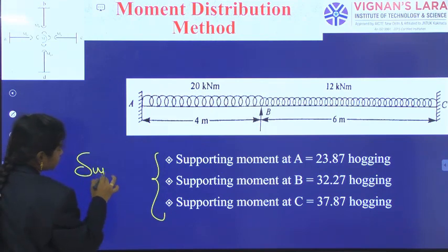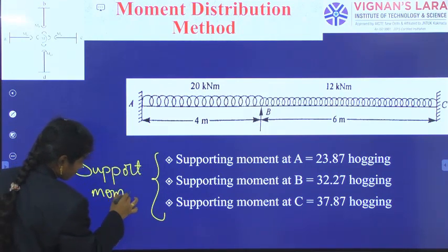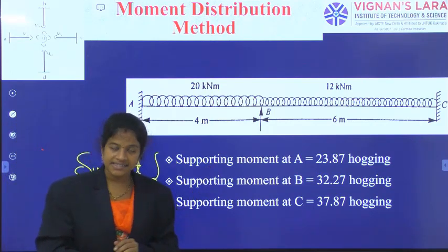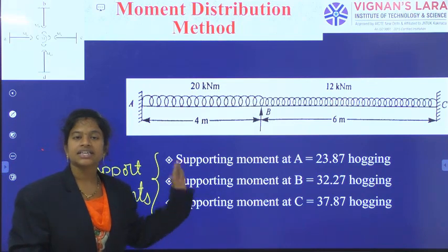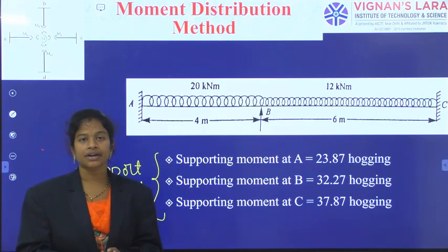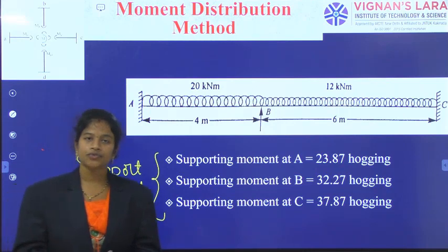So the support moment step only we have completed. Right? In the next step, using the support moments and the free bending moment diagram, we will generate the actual bending moment diagram, then we will generate the actual reactions, and then we will continue with the shear force diagram. Thank you for today's session.